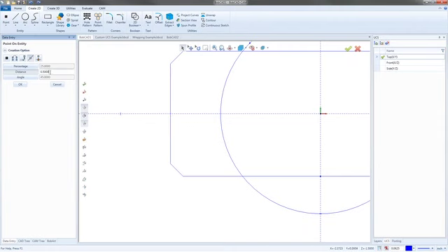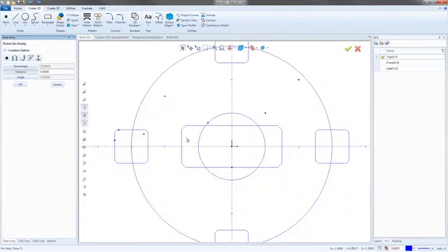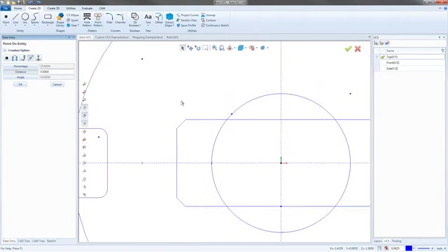My main use for the distance is when I'm working on lines that have an angle. So like this right here. If I wanted to extend this line by let's say a 1/4 inch in either direction, I want a 1/2 inch longer. What I'd do is I'd come in and I'd set up my distance, but I'd make it a negative 1/4 of an inch. And then I hover over the sides. Now, depending on which side you click on will determine which side this point goes to. So I'm going to go ahead and click right here.